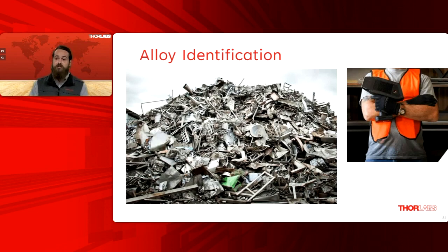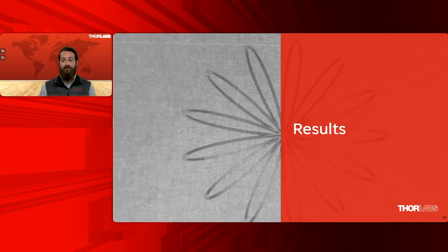As a result, they make these handheld systems here. That's a LIBS analyzer. There's a Q-switch laser in there and all the other parts we were just looking at: a focusing beam, and some way to get the light back in and measure it with a spectrometer. The user, quite simply, presses that object, which is about the size of a cordless drill, up against the part. They press a button, and now they can see exactly what kind of alloy they have. So those are some big examples.